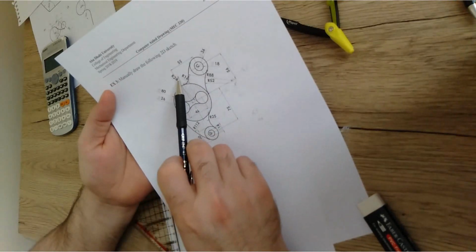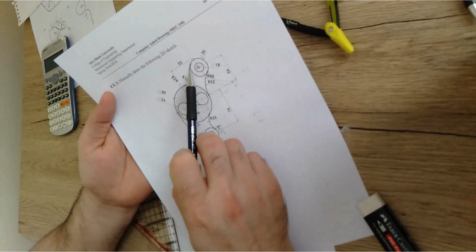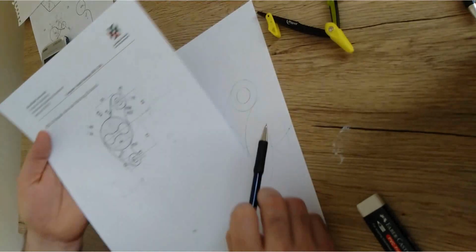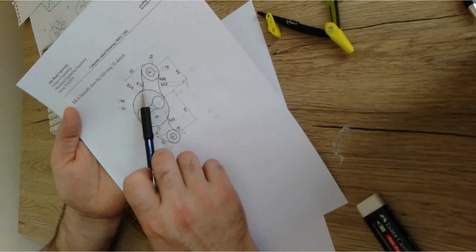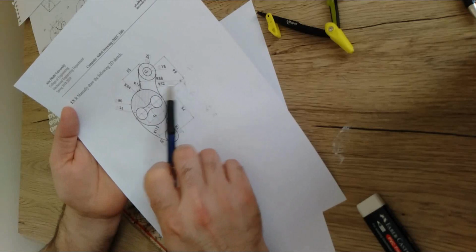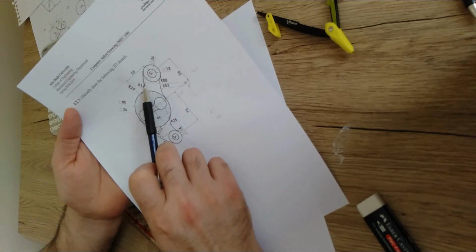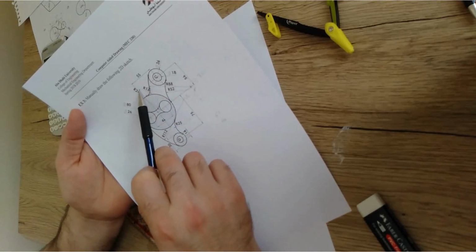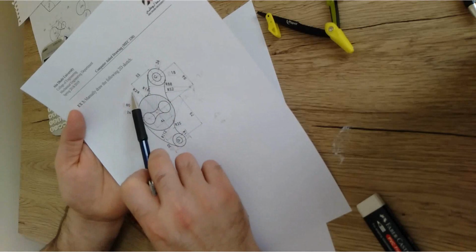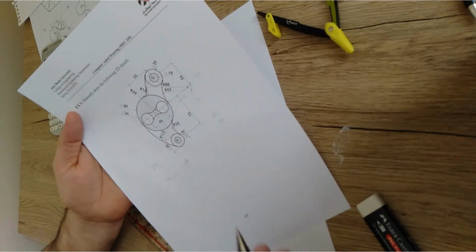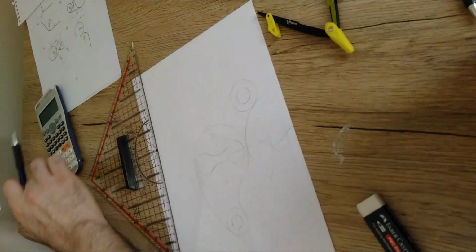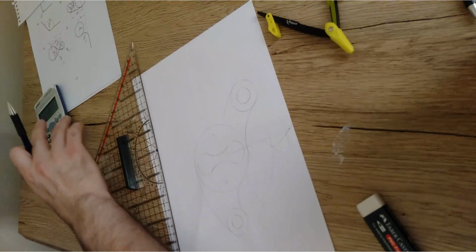If you try to move from the center, it is tangent to this curve, and the center of this curve, we define it here, right? So if I ask you to move from the center of this R16 to the center of the R88, are we going to go over the tangent point? Yes. It means that we have to sum the two radii. So we're going to have 16 plus 88, which gives 104.